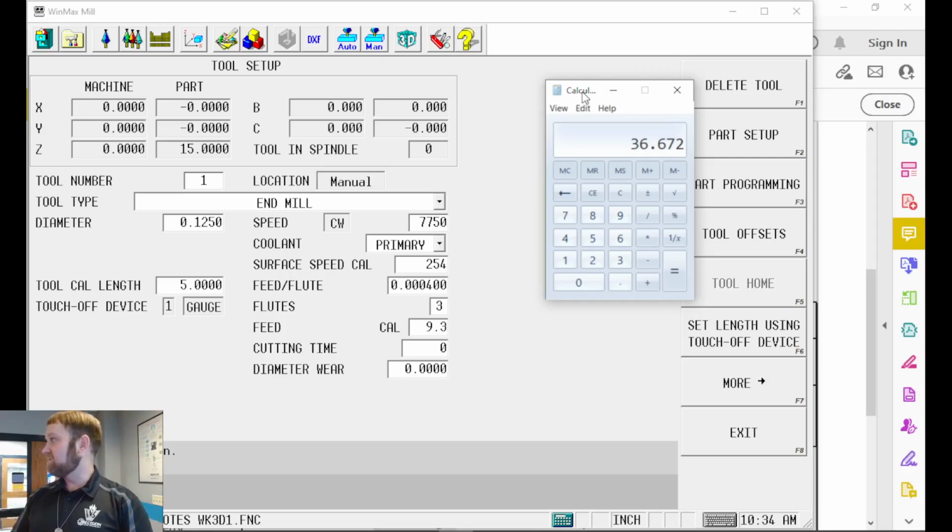If you're cutting aggressive stainless and a lot of tool steels and stuff like that, the cut speeds are so low that the RPMs are going to be low anyhow. You're not really gaining anything.